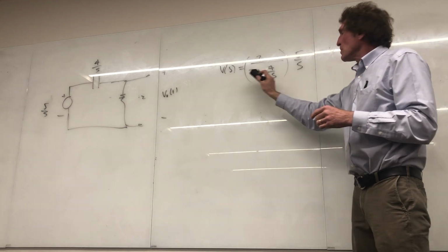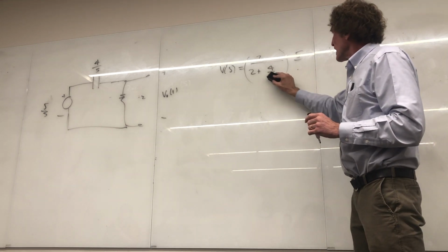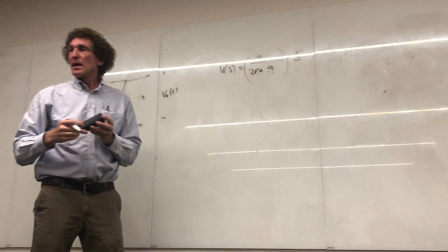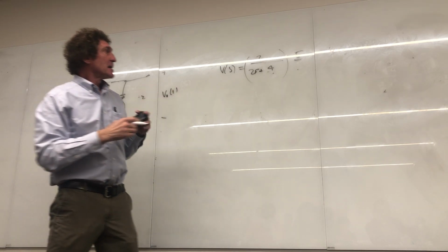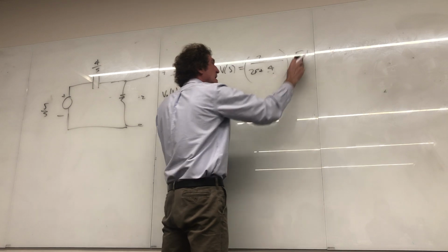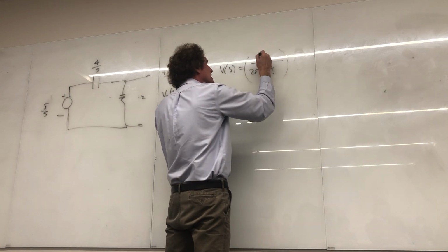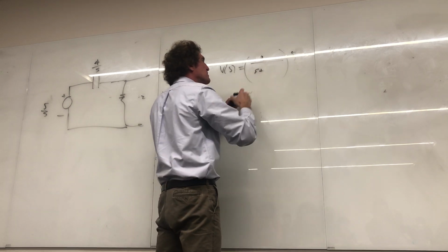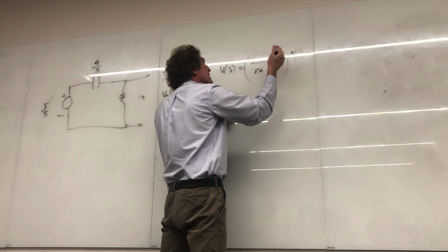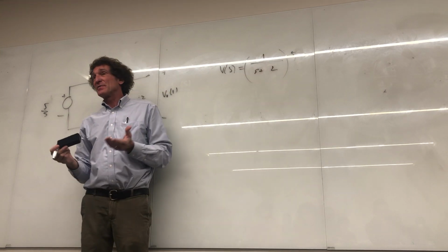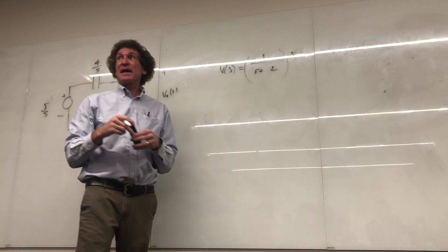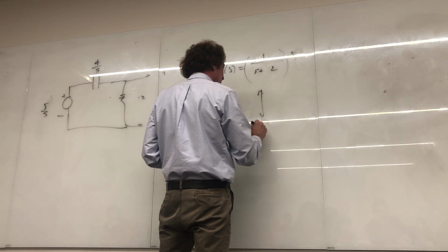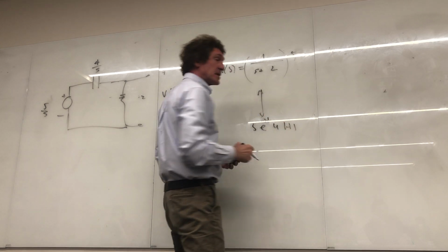All right, now, when that S is multiplied through, what happens? That goes away, and this becomes 2S, right? Agreed? Then we simply take a look at that, and that's 5 times 2 is 10, right? But actually, I should just leave it like this, because now what I'm going to do is divide top and bottom by 2, and when I do, that becomes 2, and that goes away, right? And that's straightforward, because that's just going back to the time domain. That is in the simplest form, right? It's a simple pole, and this goes right back as simply 5 e to the minus 2t u of t, and that was the output voltage for that one.